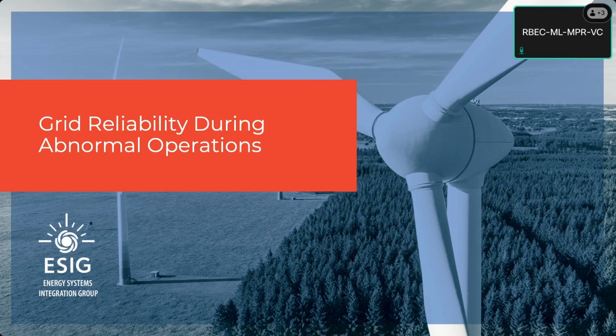Okay, so the idea is that each of these IBR plants is contributing to damping, either positive or negative, in the subsynchronous region. So when you add a new plant, maybe you have one plant that's terrible. It's really just injecting a ton of negative damping into the system, but it happens to be stable. So the system is now stable. This one plant is terrible, but the rest of the system is compensating for it. It gets through all the studies, and the whole system is stable.